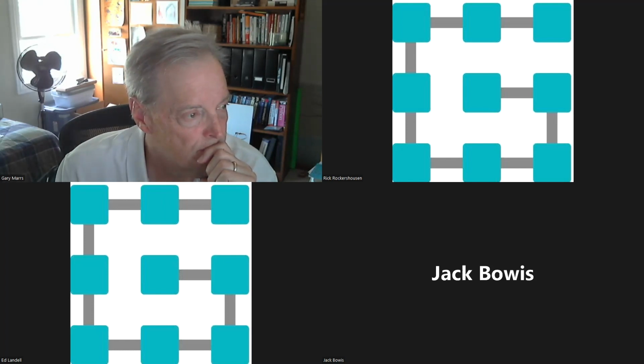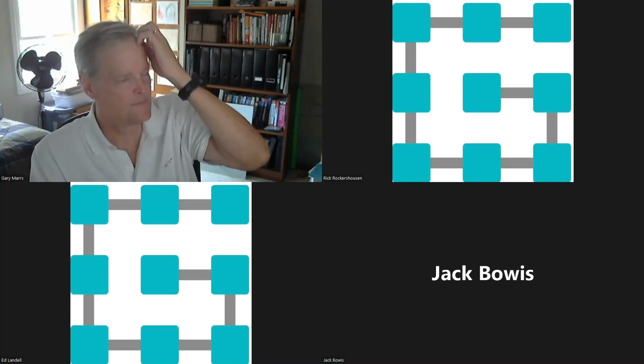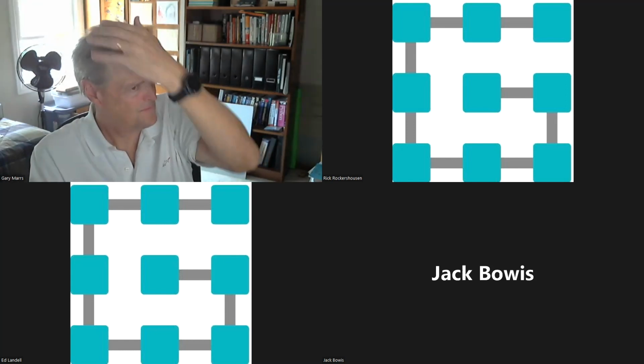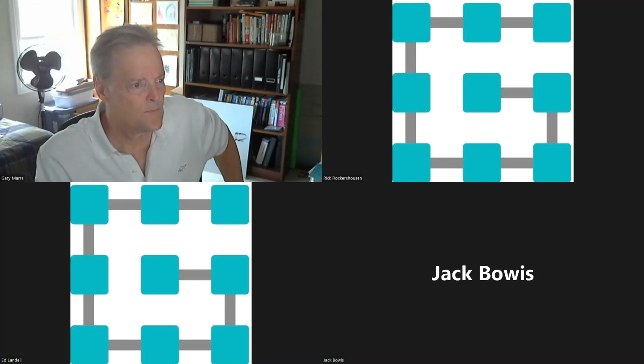I suppose there are other things you probably want to look at. Again, I would say look at termination. Make sure the bus is terminated on each end and not terminated somewhere in the middle. Yeah, that's a really common one. That should definitely be on everyone's radar. And if you have a particular node that's failing, you would try to swap that one out, like everybody would do.